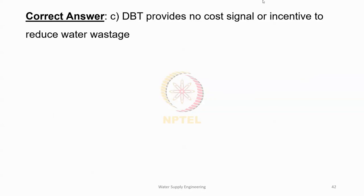Okay, so the correct answer is option C. DBT provides no cost signal or incentive to reduce water wastage, because in DBT it is like decreasing block. That is, for the first block, the unit price is much more than any other blocks. With increase in block level, the unit price is decreasing in the case of DBT method.